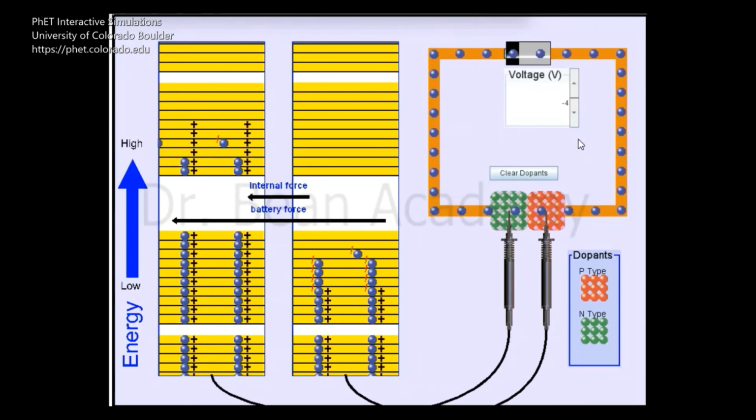I see that some current is flowing, right? But then it has stopped. Now you know the reason. In the reverse biasing, I told you that you will see some current, and that current is because of the minority charge carriers. If you have forgotten, just see my previous lecture where I have explained the function of a PN junction, and especially where I have drawn the graph of voltage and current values for both cases.